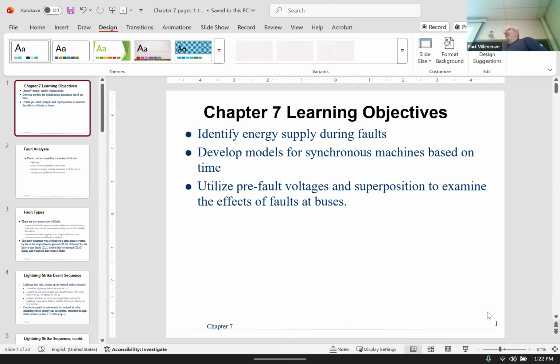But I don't know of any breaker that can do it in half a cycle. The relays can't operate any faster than 1 or 2 cycles, so you still have to put that in anyway. But if you go to IEEE, the fastest that they recommend is 12 cycles, which includes 3 to 5 cycles for breaker operation time. They just say it takes 12 cycles. So your system's got to be able to handle or withstand all that current for that period of time. But it's a good question.